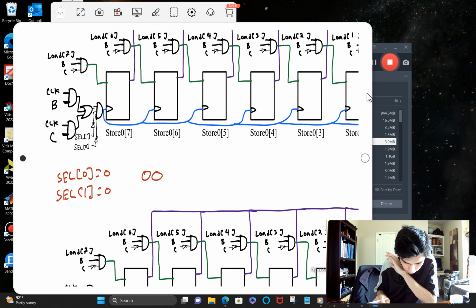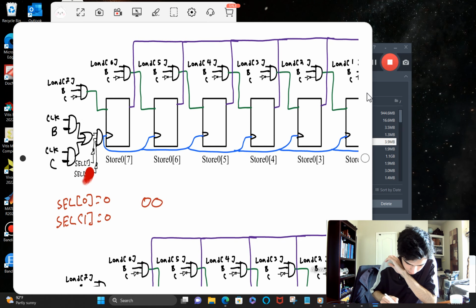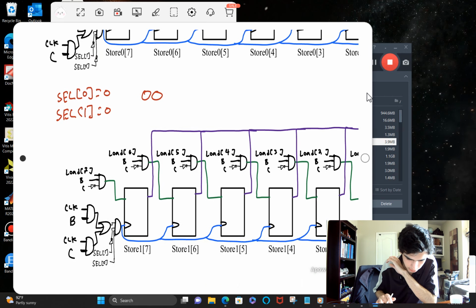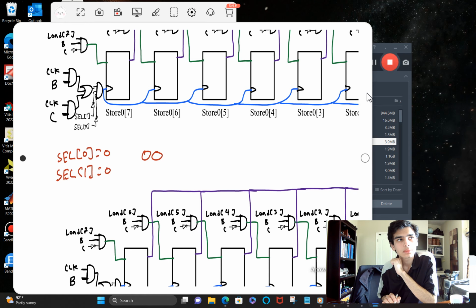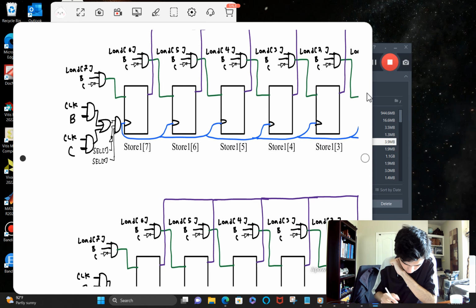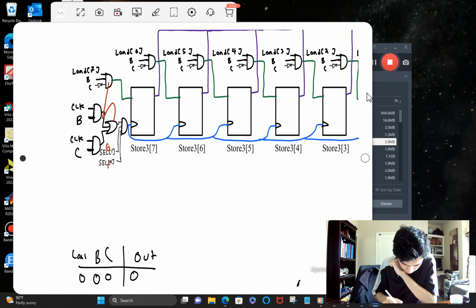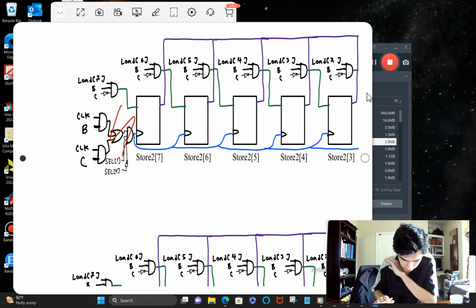So yeah, this last AND gate with the cell 1 and cell 0 and the inverters, that helps control which one changes depending on the state you're in. Because when you're in state 1, 0, 1, 1 there, 1 there, because it gets inverted. And then for all the other ones, nothing's going to happen. When you have 0, 1, 0 goes in there, so the AND gate can't pass anything. It's just always going to be 0.